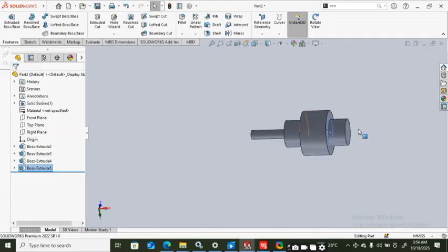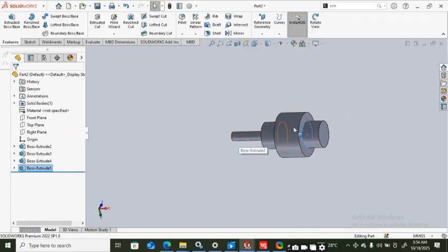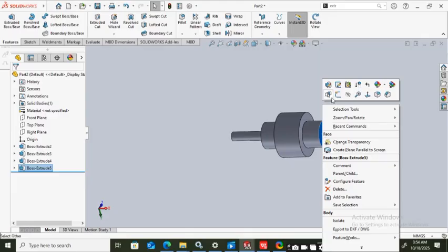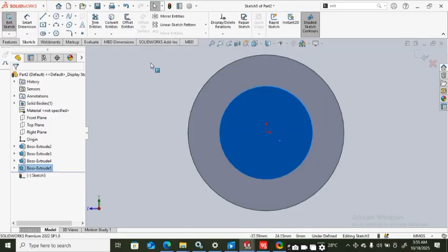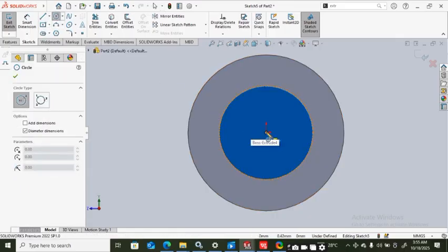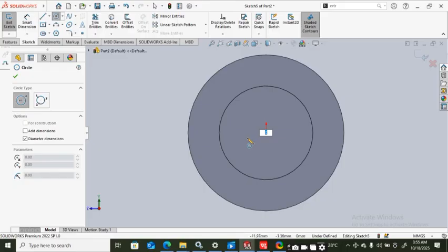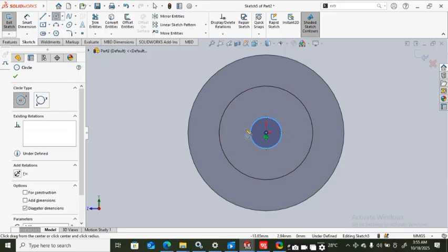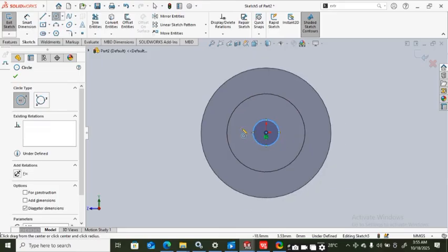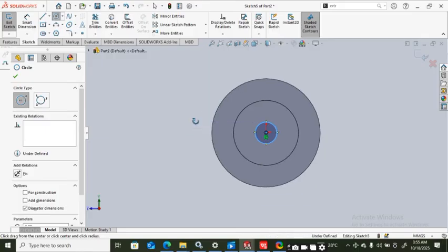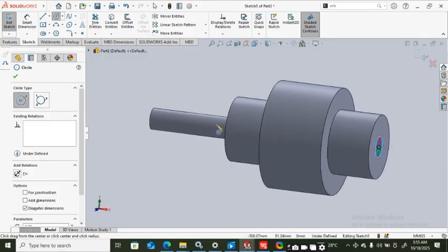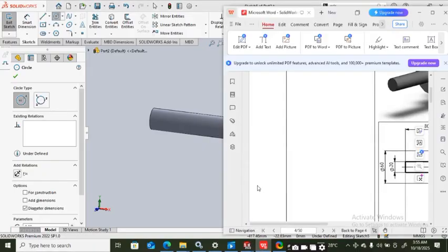So the last thing here is the last cylinder that is over here. So you move to this place again, you right click, you go to your sketch, you click your sketch, and then you go to your sketch again, right? You just click here. So we're going to dial in 20. That is the diameter of that circle. So 20, and then you click enter on your keyboard. So this is 20, and the extrusion is 60, just like the first one you see here.